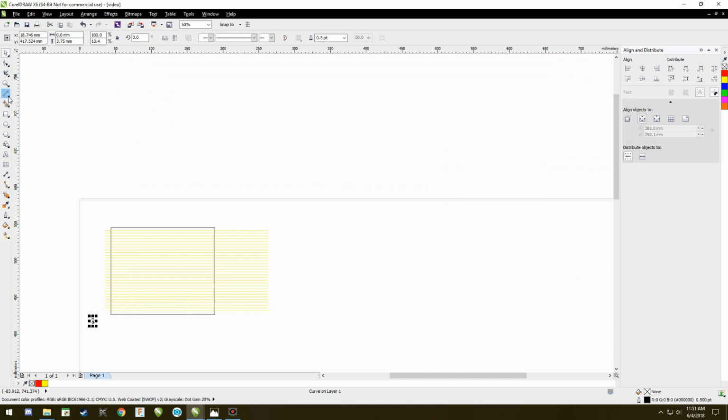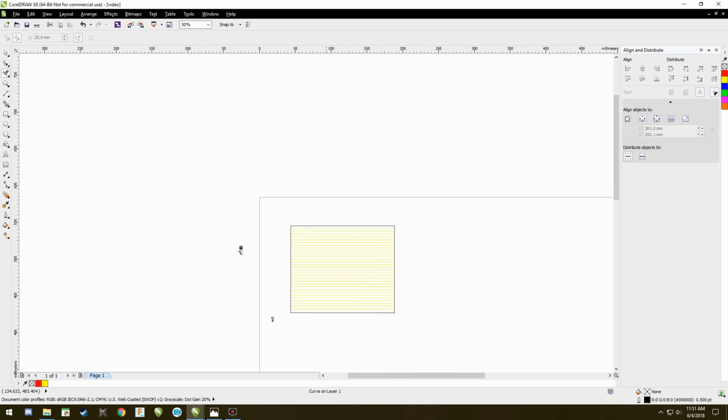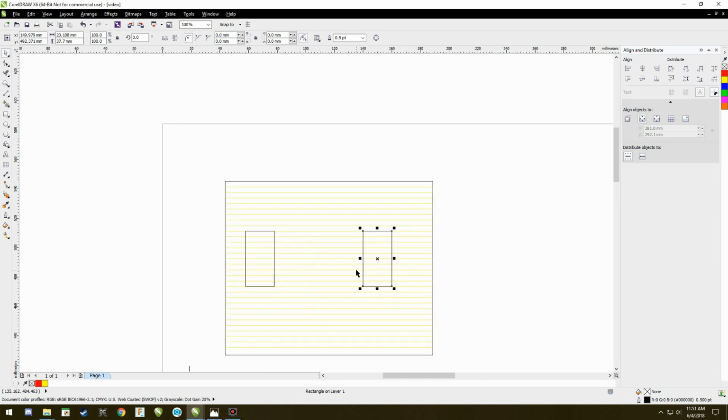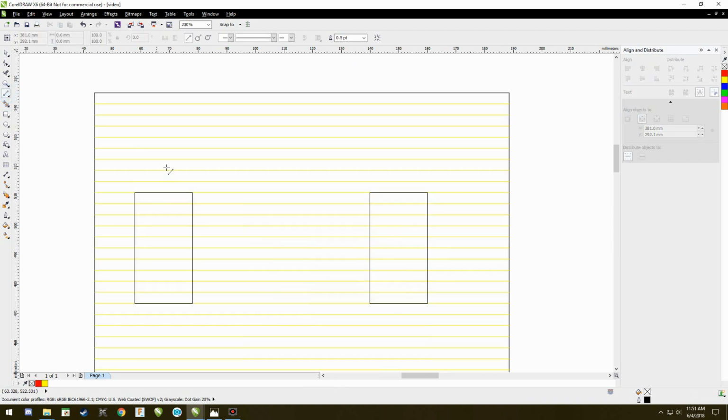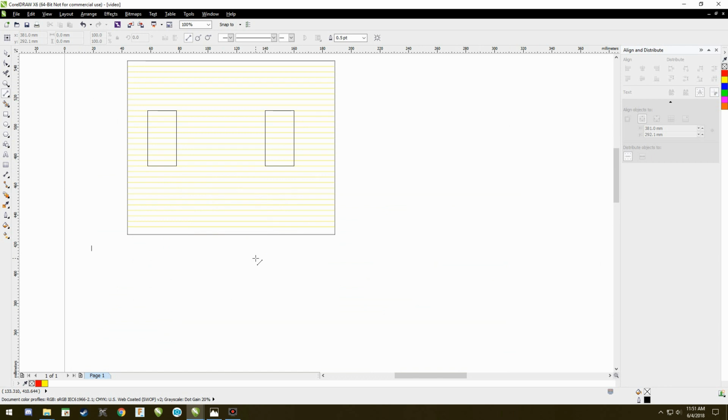And then if I wanted to trim this off, there are tools here that I can use to trim all this off. So now I only have it just on my side of the building. And there you go. And then if I was going to do a window, I could add a window and duplicate that. Maybe I put one right over here, and then I want to make sure they're the same height, so I'm going to simply draw a line. Well, actually I don't have to do that because they're on the same line already. So there you go. And that is how you could build a side of a wall. Just that simple. Not very complicated.